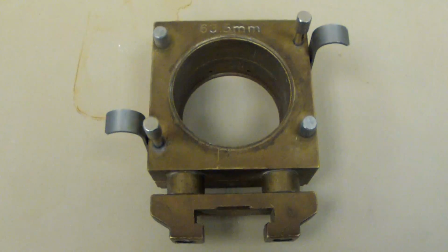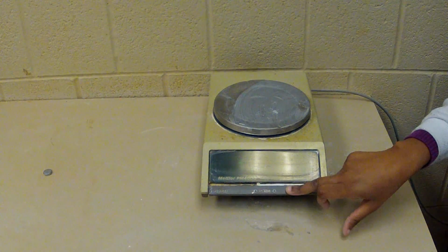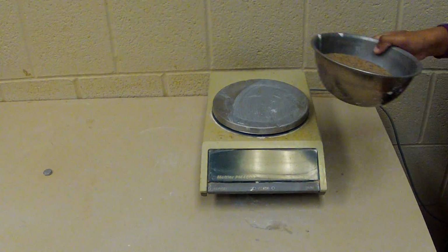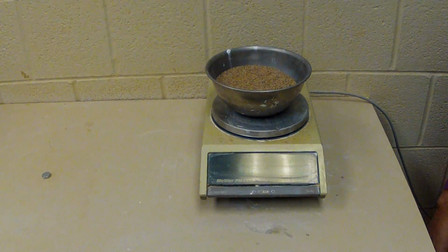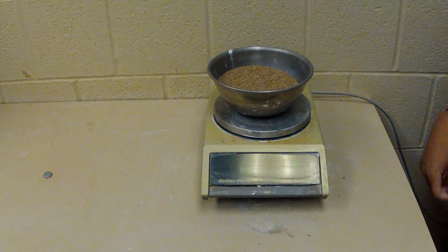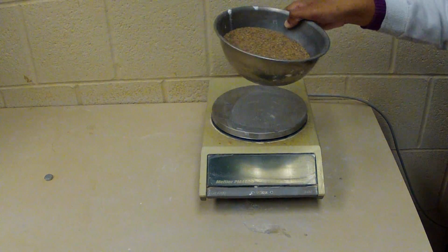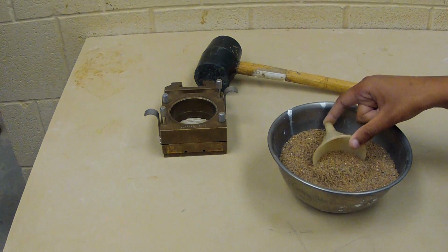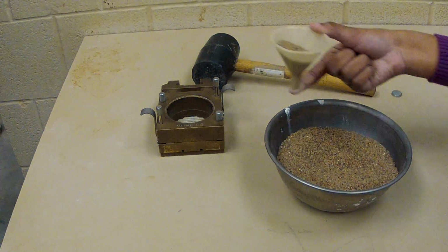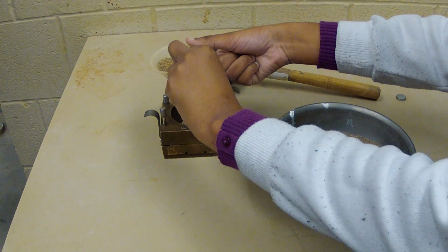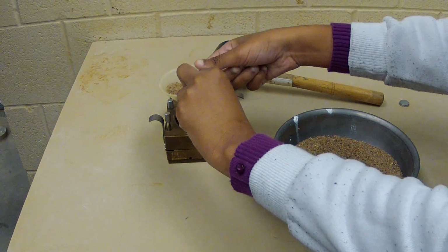Generally, one is to measure and record the mass of the shear box before and after filling it with sand, but for the purposes of this lab, we will deviate from that and record the mass of the sand in the bowl before and the mass of the sand in the bowl after we fill the shear box. This will be discussed further in the lab video.